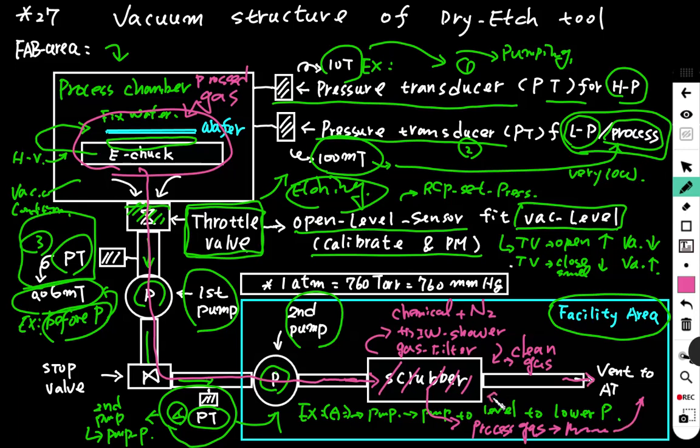So we have to keep the scrubber working very well, renew the filter, clean the scrubber and use a neutralizing chemical. It costs money, but it is necessary. Okay, see you next time.